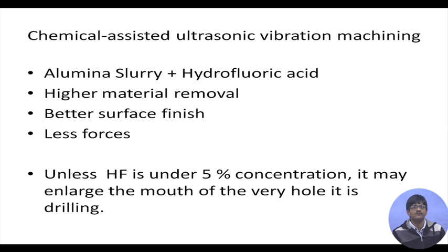Hydrofluoric acid is known to attack glasses, etc. So, a common practice in chemically assisted ultrasonic vibration machining is to add some hydrofluoric acid into the alumina slurry, and in that case material removal also gets enhanced, because chemical action associated with ultrasonic vibration greatly enhances the material removal rate.